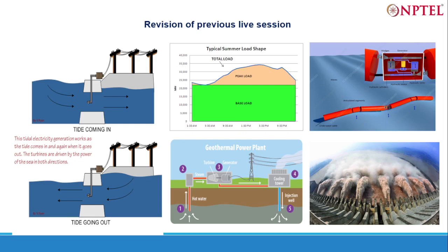Now the third one is the Pelamis converter. This was actually a very important concept for converting wave energy to electricity. A commercial scale, or you can say between commercial and pilot scale, plant has been set up on the South Korean coast, and it's working very well. It is producing electricity, and basically these Pelamis converters are based on hydraulic rams. There are some hinge joints, like here you can see the hinge joints, here you can see the hinge joints. This is the ram, this is the hydraulic fluid, and this is the turbine.